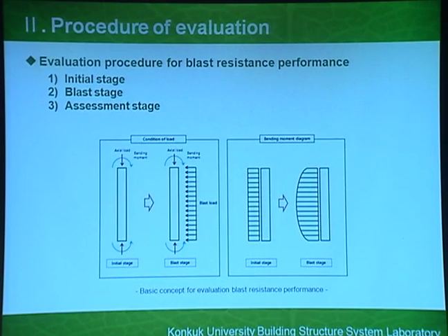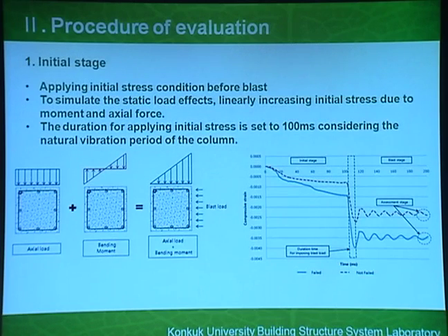Okay, we came up with a procedure to develop the design guide. We divided the whole process into 3 stages: the initial stage, the blast stage, and the assessment stage. The first one is the initial stage, which applies initial stress before the blast. We found that this initial stress strongly affects the structural behavior due to blast load, so we should apply this initial stress condition.